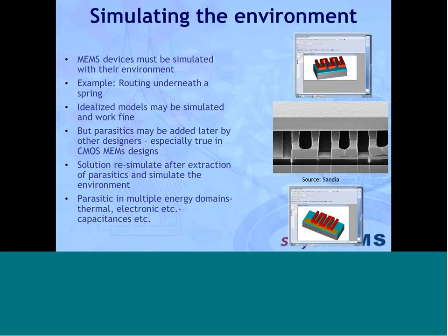And then a very important issue that we also want to take into account is the fact that we need to simulate the environment along with the MEMS device. So we need to take into account that we may have a MEMS structure, but then after the structure itself has been created in mask layout, we may be adding parasitics by routing wires and putting other structures next to our MEMS. So with the MEMS Pro tool suite, we can do things like re-simulate our devices after they've been routed or put together with their packaging.